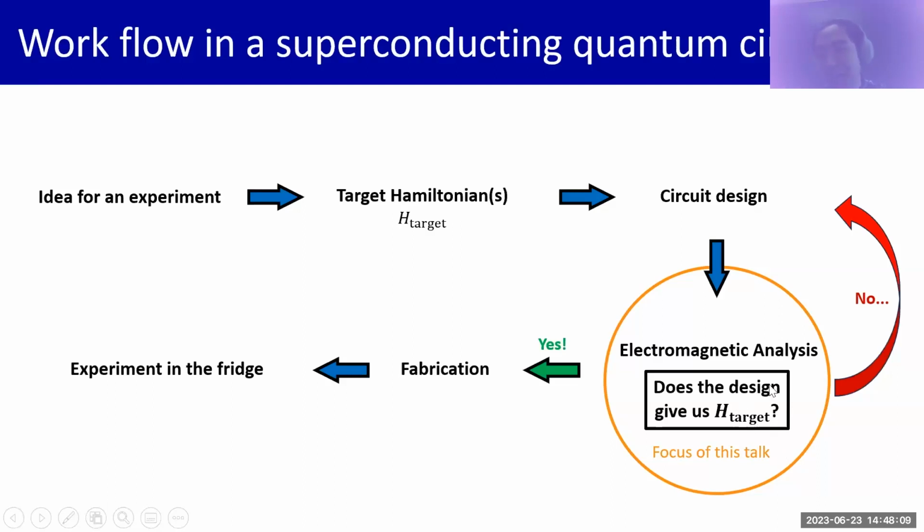And usually the Hamiltonian we want is just a dispersive Hamiltonian with the anharmonicity of the transmon and cross-Kerrs between the transmon and any modes, etc. So what I have shown you is generally designing in HFSS, simulating, and using the PyEPR package to evaluate that. And if that gives you the parameters like chi's and anharmonicities that are roughly what you need in your experiment, then it's good. You go to the next step, or you just go back to modify the design and simulate it again.